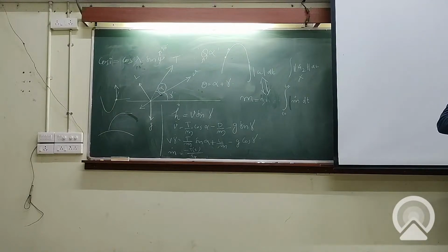The first burn is called a boostback or a boost forward. That is primarily to adjust the range. You have to cover a certain range to go and land at a designated location. So for the boostback or boost forward, depending on where you are heading, you have to optimize the burn duration, not just the burn duration but the attitude of the burn, all those things.